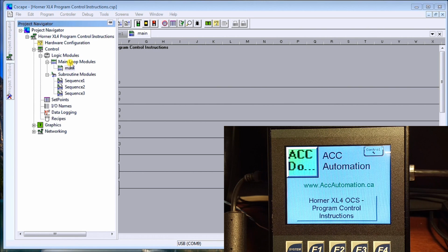And in order to get a new main code logic, you right click on the main code and you can hit new enhanced ladder logic block. Also, if we look at the main one here, we can exclude certain ones from compilation, which actually means that we don't have to run that code if we don't want to. And subsequently, if we look at the subroutine module, we right click, and you see the new enhanced ladder logic subroutine. We just add new modules there.